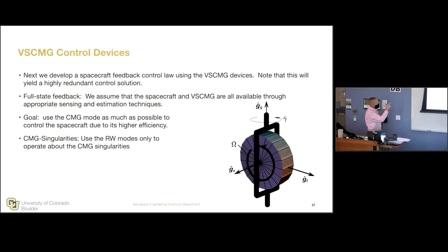And when we develop this, we won't see this at the beginning, not today, but later next week. At some point, we have a lot of options because we tend to have 4 of these devices, 2 control inputs. So with reaction wheels, you have 3 or 4. Rarely do you have more than 4, but that is possible. Here we have clusters of 4 CMGs where I get torques from gimbaling, but I can also increase or decrease the wheel speed, which gives me different torques. So I get 8 control knobs for a 3-dimensional problem. We will have a lot of options. But that's good, because there's a lot of challenges. There's gimbal lock, there's all these elliptic and hyperbolic singularities, and all the other stuff that appears.